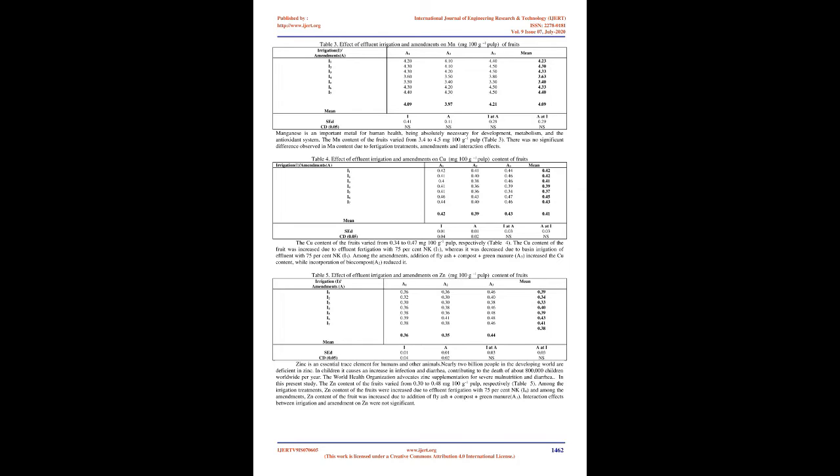The drip system consisted mainly of control head system, filter, dosatron, and distribution network system: main, sub-main, lateral and dripper. The equipment used for fertigation, i.e., for injection of fertilizer solution into the drip system, was dosatron, a doser pump. The fertilizer stock solution was sucked from the tank installed below the dosatron by a suction tube of 1.2 m long. The injection rate was regulated by adjusting the graduated scale provided in the injector body of the dosatron.